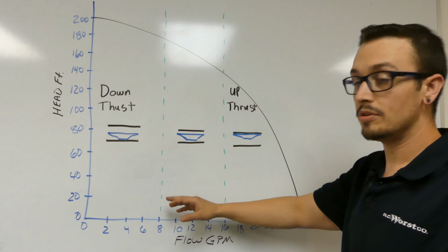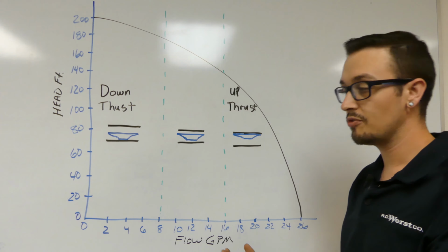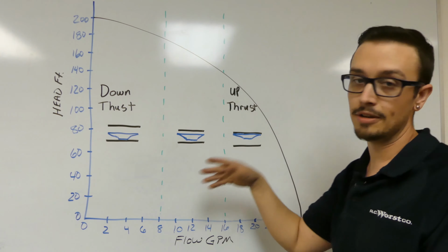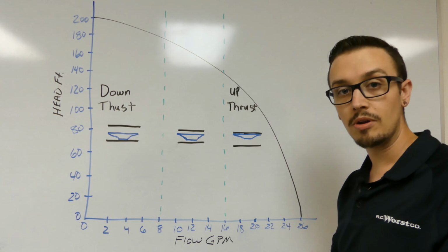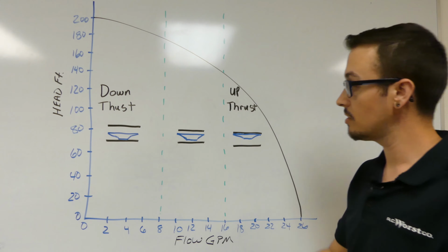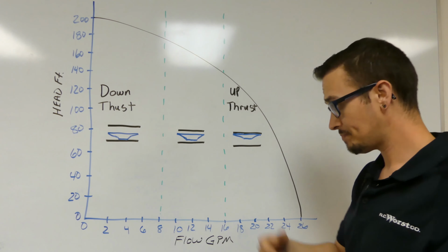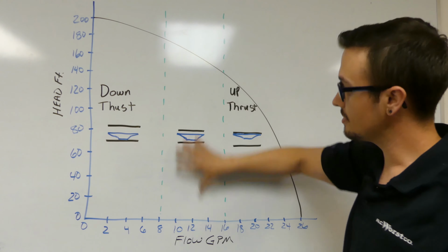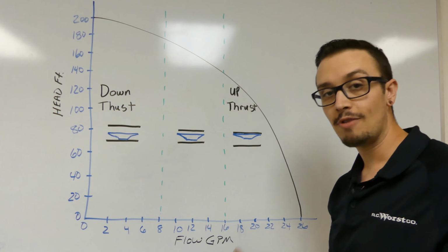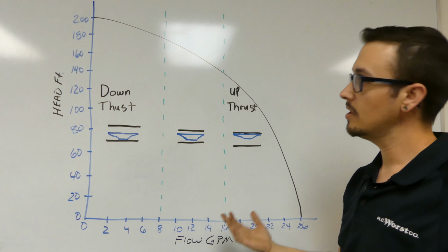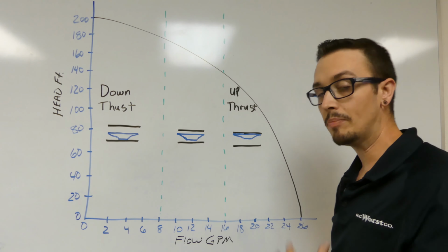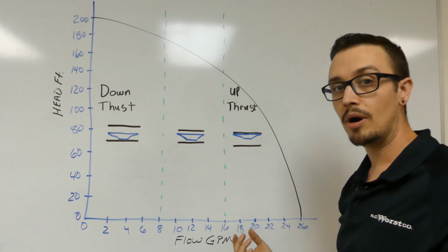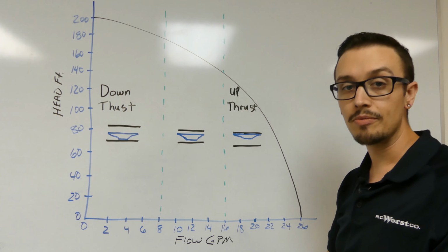What you might have noticed if you've looked at pump curves before, specifically submersible well pump curves, is that oftentimes there's an area that's either shaded in blue if you're looking at Franklin Electric pump curves, or in the case of A.Y. McDonald pump curves, a green shaded area. This green area, where I've put the dashes, in the middle is what's known as your recommended operating range. When you look at a pump curve, especially for a well pump that has multiple stages, you want to operate that pump in that recommended operating range.